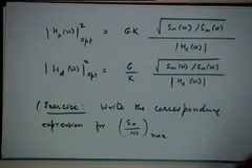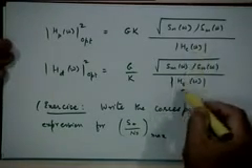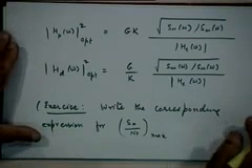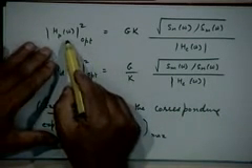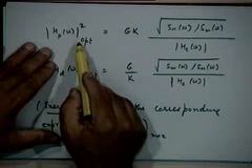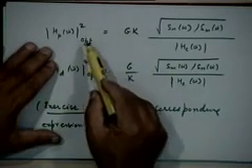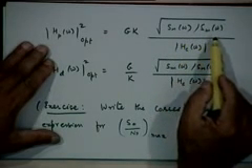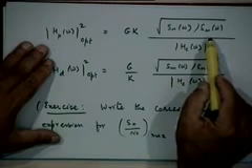Assume for our discussion that H c omega, the channel transfer function, is an ideal transfer function, right? That is, over the bandwidth of interest, this magnitude is equal to some constant, let's say equal to 1, right? So this goes out of our consideration for this discussion, right? So what are we saying? That the pre-emphasis filter should have a transfer function magnitude square which is proportional to the ratio of noise power spectrum to the signal power spectrum, right?